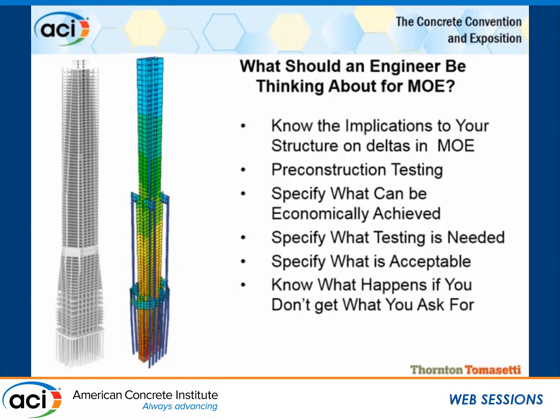And the taller you get and the more slender, the more possibility you're going to be doing a very novel mix at some point that's never been done before. So you've got to do the pre-construction testing to know what modulus you end up with. We have to specify what testing is needed, and we have to be very clear about whether the tests are part of the acceptance criteria for the concrete. We know that contractors are risk averse, that if they have low-strength concrete in the job, it's a big problem. Modulus right now is in a bit of a gray area that needs to get resolved in the engineering and specification community.